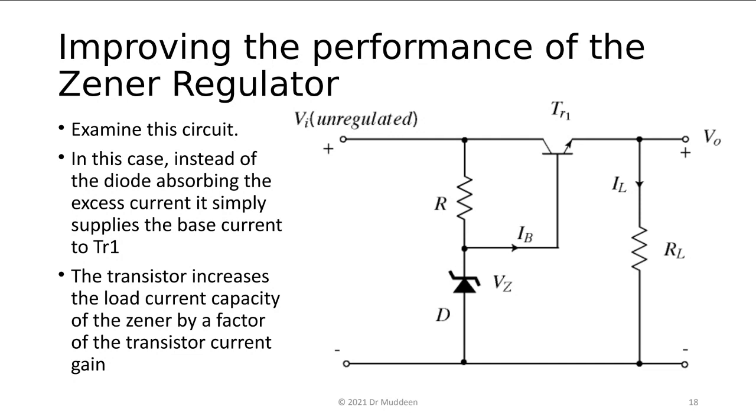Right, but here's the thing. You don't want to be in a situation where you design the circuit and the Zener diode starts to get hot and you say, oh wow, take out the diode and put a bigger one. You want to do that up front. Just think about it. Let's say you make a power supply for a friend and they take it home, and the thing starts to get hot. It's in a case and it's sealed up and it's getting hot. You can't tell them, hey, let me swap that Zener for a bigger diode, for a bigger wattage.